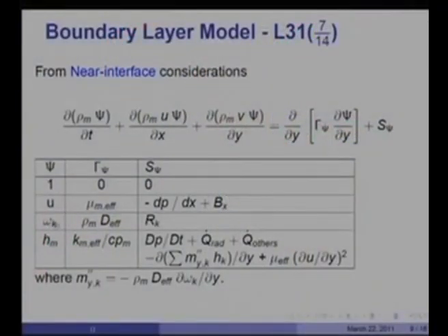And remember, there can be several species in a given problem. Evaporation of water is the simplest because it has only two species. In combustion problems, where a chemical reaction mechanism can involve as many as 40, 50 species, then of course, what it means is that you need to solve so many species equations along with the momentum and the energy equation. So, the mass transfer problem can be very big. It depends on what kind of reaction mechanism we have specified. In the absence of chemical reaction, life is simple, and you would simply need to solve momentum and energy equations.